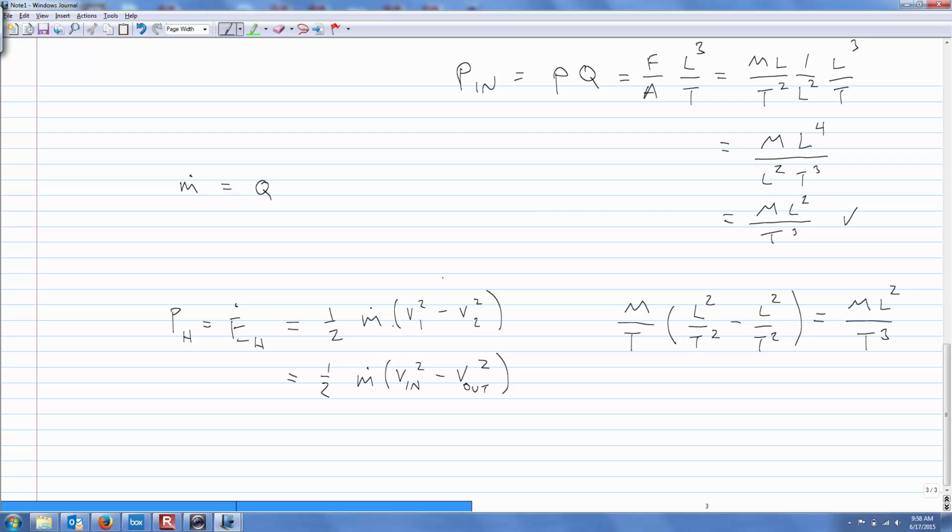So if I multiply the volumetric flow rate, we'll be able to go and look that up. I mean, you can look up what the volumetric flow rate is of the Clark Fork River or whatever little stream you have, and that's going to be the maximum flow you could possibly get. We typically augment this by building dams. We don't have that option here, but if you were able to stick your barge out there and shove all of the water in the Clark Fork River, that would be the maximum power you would expect to get out of this thing. So if we know the density of water, we'll be able to get to our solution.